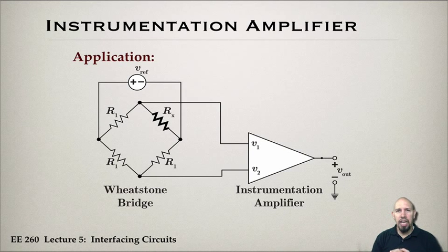But having this basic understanding of circuits can be helpful when it comes to interfacing the Arduino to the real world, to sensors, actuators, and other things like that. Having the basic concepts of, for example, voltage divider, a Thevenin equivalent, knowing how to work with some basic op-amp circuits, knowing what input impedance and output impedance, or input resistance and output resistance are. Knowing these basic quantities now can help you when you want to connect circuits up from one circuit to another. Understanding what's needed and what's good, that's a helpful thing.